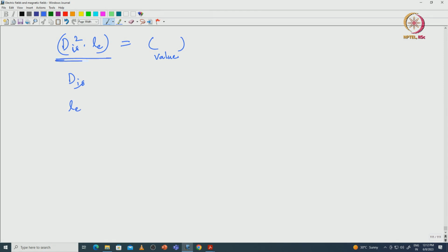We know only the volume product, whatever equations from 1 to 9 we have seen, we can get some value, but how to get the individual values, like what is the inner diameter of the stator and what is the length of the stator? To decouple these two, we have to consider the parameter aspect ratio.